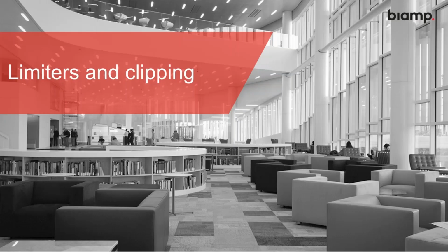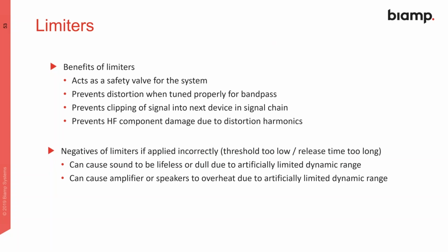So getting into limiters and clipping, we'll jump right into this. Some of the benefits of limiting: it gives you a safety valve for the system. Basically, it makes it dummy proof. If somebody accidentally boosts the 500 hertz EQ by 12 dB, or pushes a fader way up, it acts as a kind of backstop against that just being passed right onto your speakers.